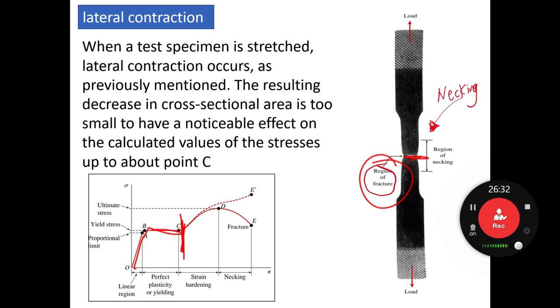The area that we are dealing with, we call it the total area, or the area without contraction. After that, the area is going to decrease. There is contraction here, but commonly, engineering wise, we neglect the contraction and we say that we are going to use the whole cross section.